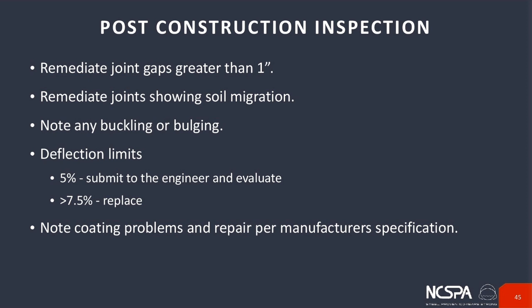You also want to note any type of buckling or bulging, or any point loads in that structure, and really just make note of it. Make sure it's not growing. And then notice the deflection limits. At 5%, you probably want to take that to the engineer and evaluate it. Greater than 7.5%, you're going to need to replace that structure because you're exceeding your limits.